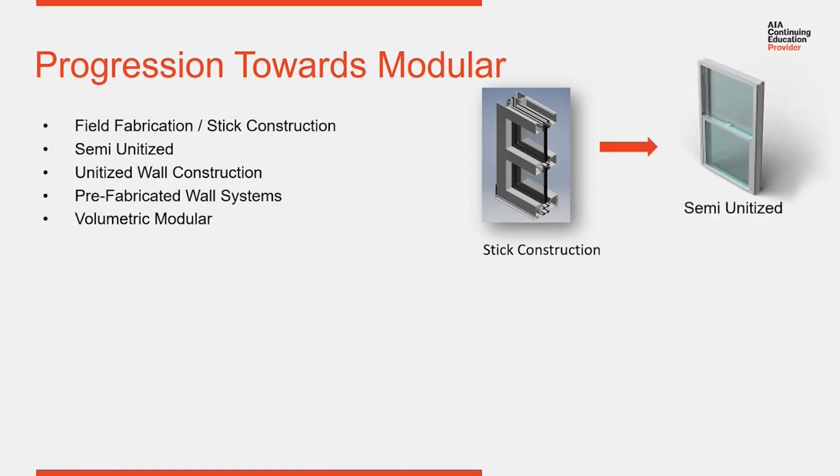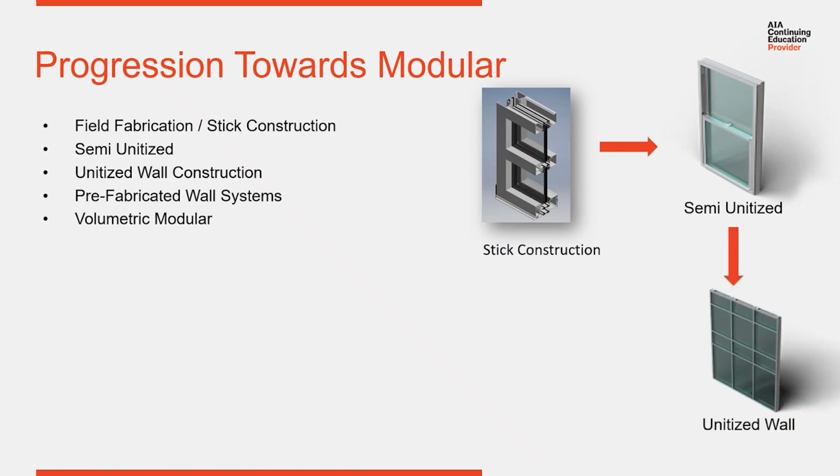When we saw growth in commercial windows, the model with commercial windows was different. Manufacturers wanted to pre-build their windows and pre-glaze them, and they were shipping them out as a pre-built glazed unit ready to go into a punched opening. So a lot of times commercial windows were going straight into a punched opening. So there was a rough opening there, and then the window set in, boom, it's closed up. So we saw windows starting to kind of model how we can pre-build and pre-assemble things.